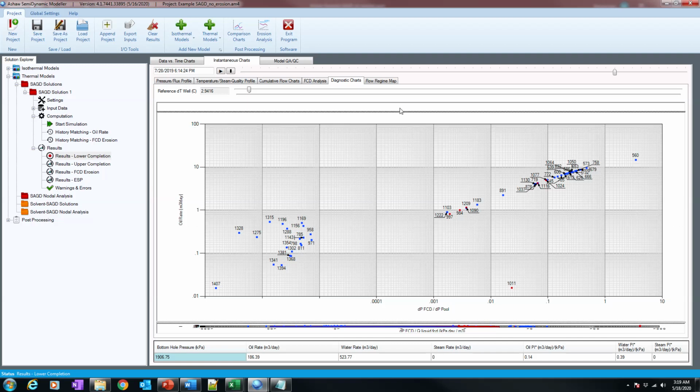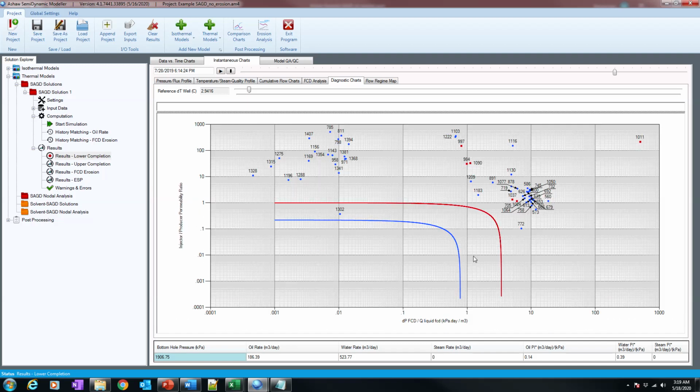The other chart here on the bottom tries to show you about the stability happening as a result of changing the permeability inside the liquid pool, or the permeability change between the producer and injector. So in a lot of cases, once the injector permeability is low and producer permeability is high, you start having instability happening. And in those cases, the flow control device has to choke more.